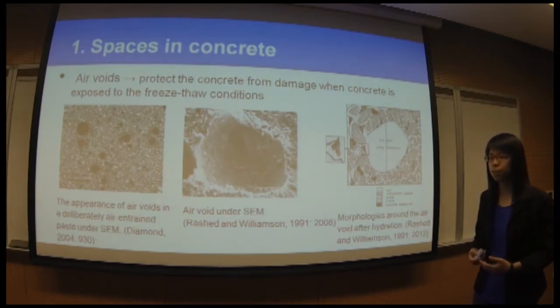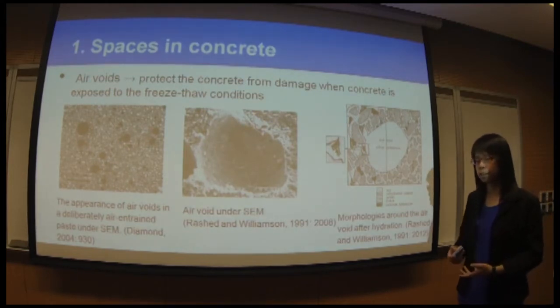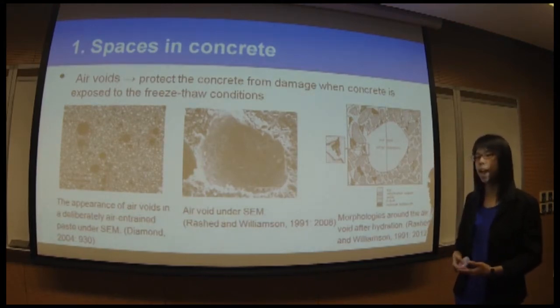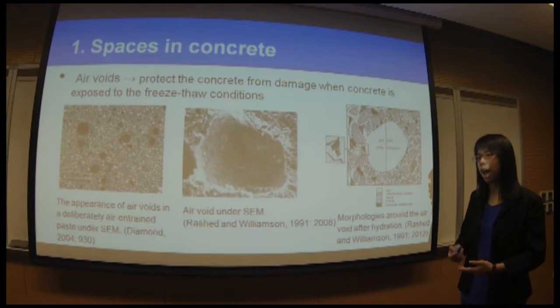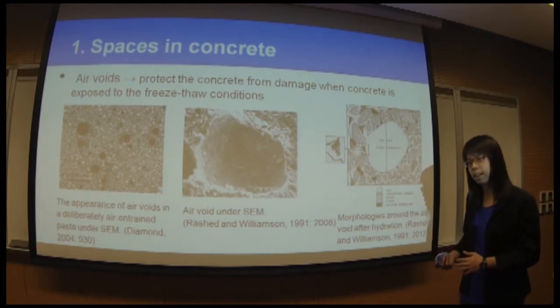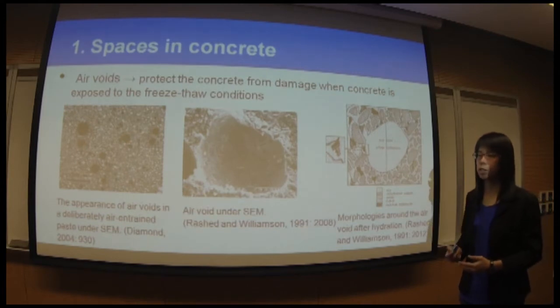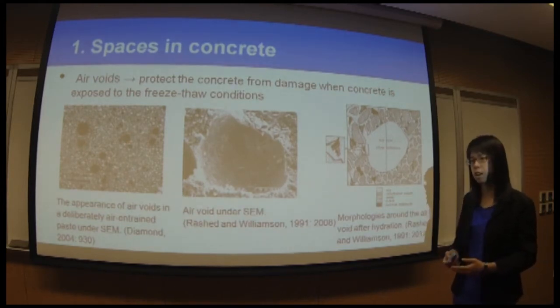So when the silica fume is added to the concrete, the silica fume particles will react with the cement grains, and then calcium hydroxide will be formed, and therefore there will be an internal deposit of calcium hydroxide in the air void.